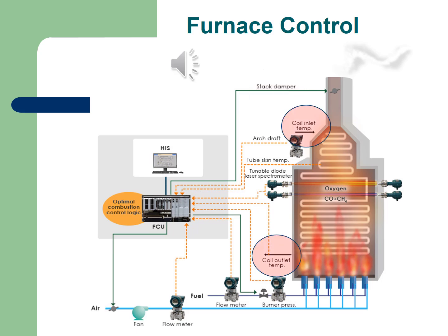Moving from the stack control itself, you can see that you have your coil inlet temperature, so we need to measure that. Usually this is quite nice when we move to control strategies, especially if you want feed forward and feedback. So if you have a very large system, it's always advisable to also measure the coil inlet temperature and the coil outlet temperature, and sometimes also the flow, so we know how much is actually flowing through the system itself.